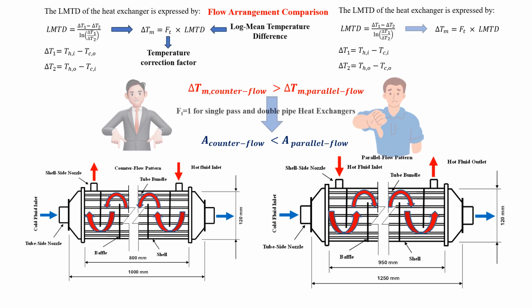And that means in a typical calculation, if we have specified the heating load and we know the conditions of the inlet and the exit temperatures for both fluids, then finally we may estimate the surface area required.